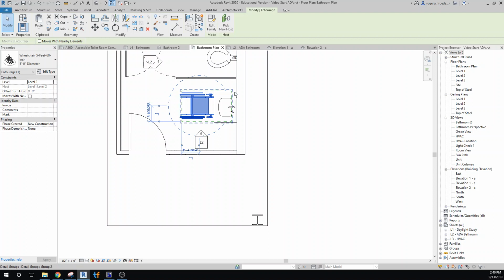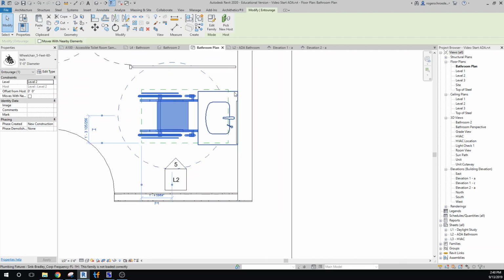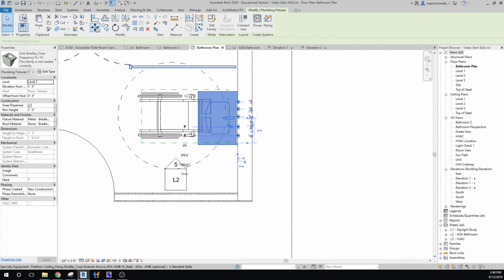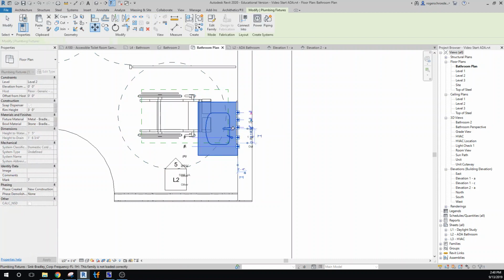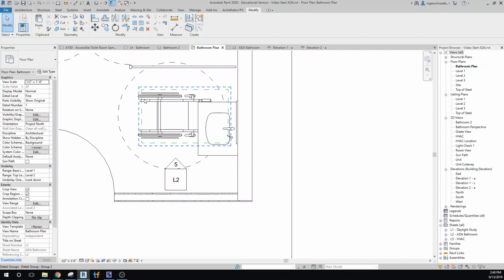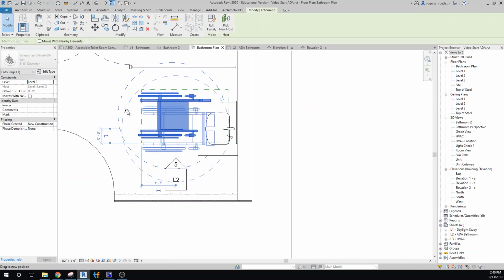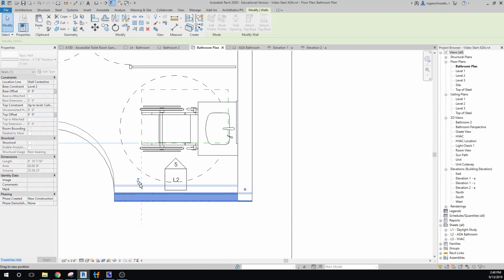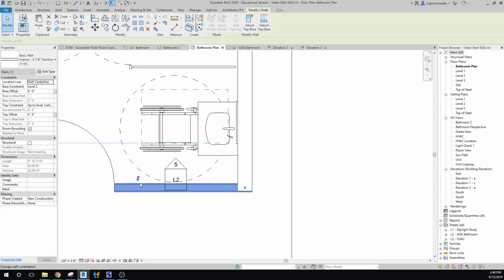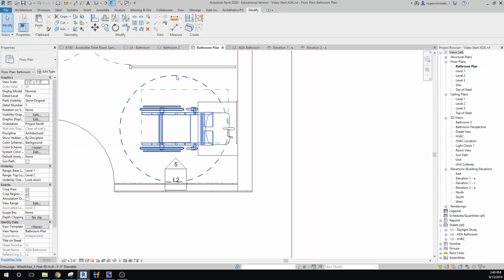let's do this. Let's be generous. Let's take this sink and we'll move it down. Just move it down 6 inches. And what I want to do is move the wheelchair down so that we're kind of aligned right in the center of that. Now we have plenty of room, generous amount of room here. Let's just move this up a little bit. Now these are all minimums, so we don't have to be tighter. We can make them more generous than they're required.